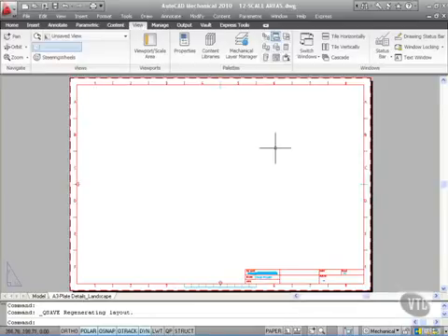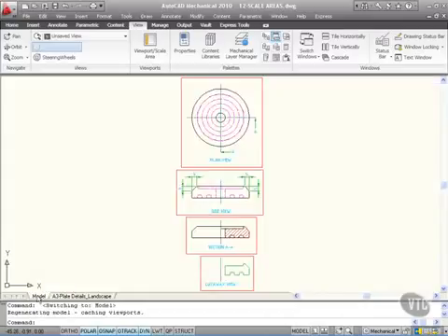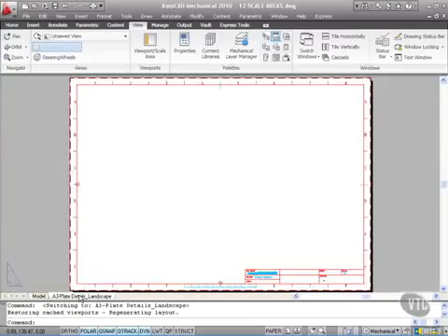The main difference between AutoCAD and AutoCAD Mechanical when you're creating viewports is the ability to utilize what they call scale areas as viewports. Now, in my model tab here, you'll notice I've got scale areas set up for each view. None of these views, however, are in the layout tab right now that I've just clicked on.